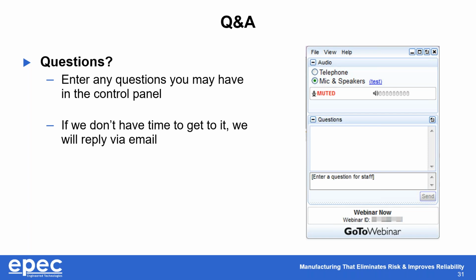This is something that we work with our customers on. We review the design, identify the shielding requirements, and from that, in many cases, we'll put together an initial Gerber file of the shield layer, submit that back to our customer for their review. We'll have further discussion, optimize it as required, and move forward from there.